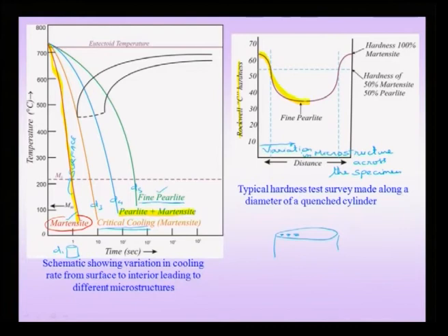interior. So, therefore, now I need to worry about the fact that if my sections are very thick, there is going to be a variation in microstructure, and therefore, there is going to be a variation in properties. That means there are no uniform properties that the material will have, and whatever tensile properties you measure would be an average. Sometimes this may be beneficial, because sometimes you would want a hard surface and a tough interior. So, such a treatment would automatically give you a hard surface and a tough interior, but then understanding the deformation behavior of such a kind of microstructure could be rather difficult.